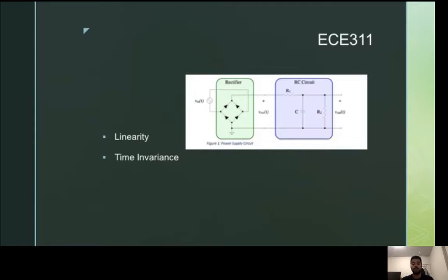And when we add the input and the reverse polarity input, the output would be double but the input sum is zero, so it doesn't obey additivity, which means the rectifier is not linear.